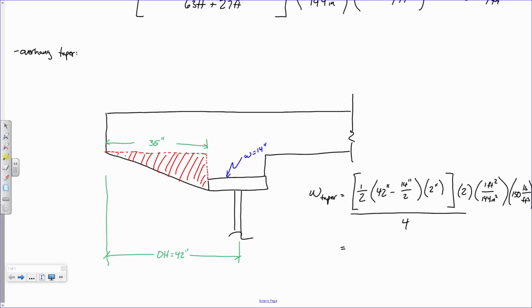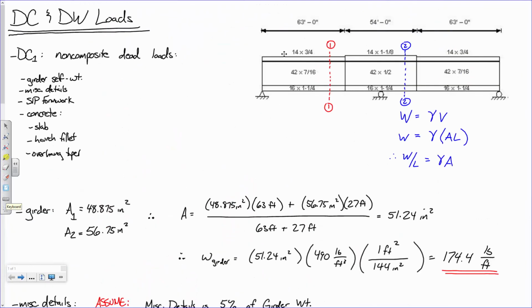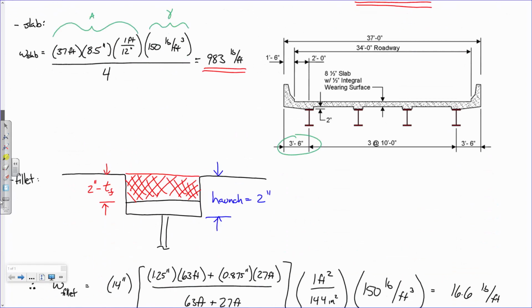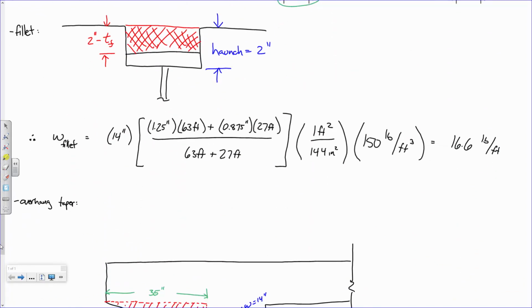Now, that's one reason. The other reason for having a haunch in general is because your flange, the top flange up here, it changes thickness. So what we'll do is we'll say, well, the flange gets thicker, but we'll sort of say, okay, 2 inches up from the web, that'll be where the deck is. You see what I mean? So, no, there isn't really a requirement, but generally, you're only providing a haunch just to ensure that you've got an even geometry. Your haunch ends up being a little bit larger when you've got really, really long spans and really large girders.